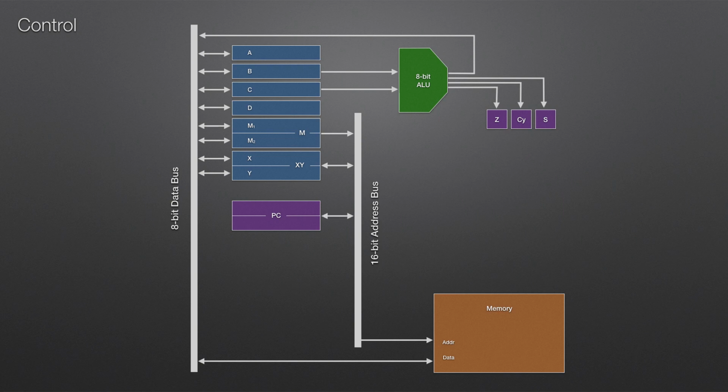This is just simply a 16-bit register, and it will just hold on to that address location. Now every time we do a part of the program, every time we do a line of the code, we need to advance the program counter on. And as you can see, there's no way of getting to the ALU from here, so what we do is we have a custom 16-bit incrementer. And what this can do is this can add 1 to whatever value is on the address bus.